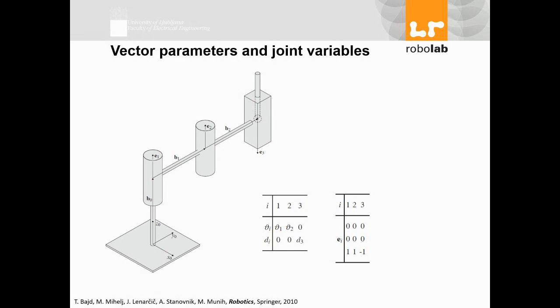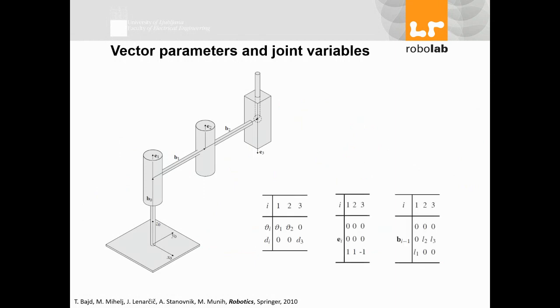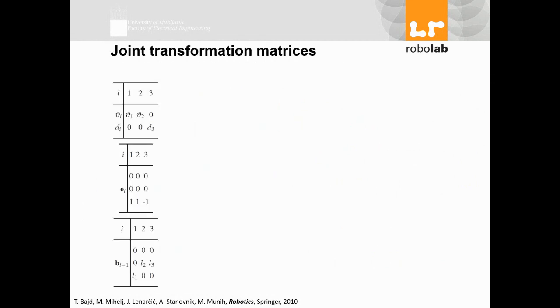And then the joints, as you could see here, the sizes, it's L1, L2, L3, right? So in terms of sizes, I have L1 in Z direction, L2 in Y direction, and L3. So this is L1, this is L2, this is L3 in different directions. So using D3, I can write my homogeneous matrices again.